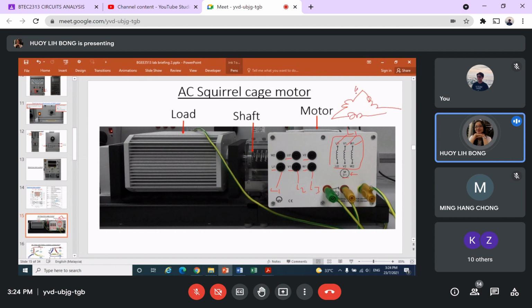So let's say I have U1 here, U2 is here, and it's connected to the next winding, V1. Here we have V2. Then we are left with the W winding. Here is W1, and here will be W2. This is a delta circuit. You can see it's a circle.